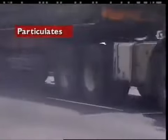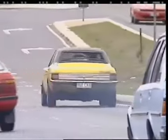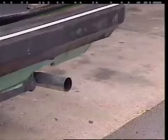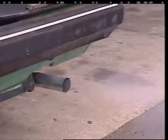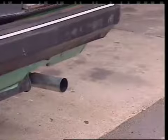This section examines particulates. Particulates from modern engines are usually carbon-based. Older vehicles may produce lead-based particulates. This is caused by lead compounds used in the fuel to raise its octane rating. In spark ignition engines, particulates are caused by incomplete combustion of rich air fuel mixtures. In compression ignition engines, they are caused by a lack of turbulence and lack of oxygen.